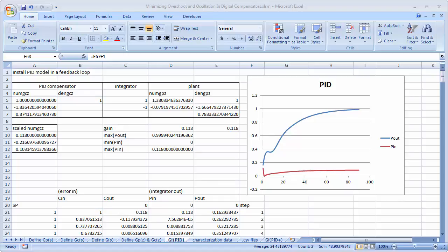We start with the set point in some modest value, say 10% of the input range. Then we abruptly step the set point to a new value and collect data while the system settles on and regulates to the new set point. This data set includes all effects: the PWM timer system, the power electronics, the ADC converters, and system noise. Since we are measuring data in system, all effects, known or unknown, in the real physical system are captured. If it's in there, we are measuring it.